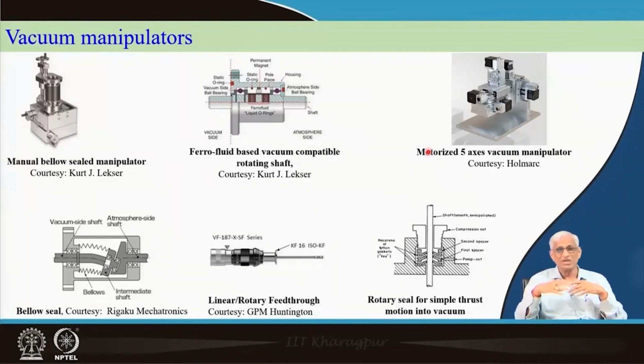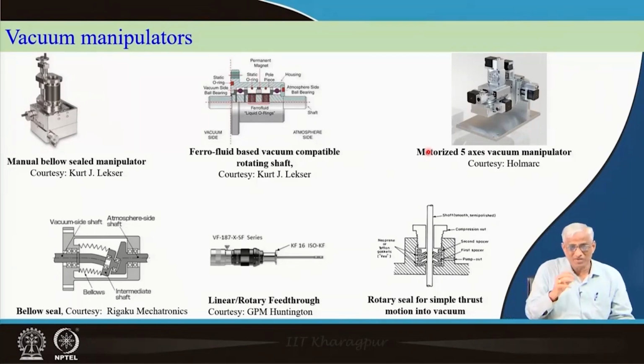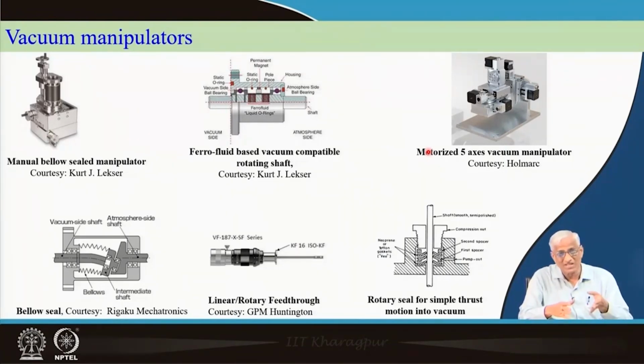If it is ultra high vacuum, all metal. If it is normal vacuum, the seal portion can be neoprene or some other Viton gaskets, like that. So, you must have a good knowledge of materials which we have already covered in the last class. If necessary, you again go to that class. Then with these things, we will go into the next class, where we will be discussing chamber design and thickness calculations. Otherwise, you will end up purchasing an unnecessarily large amount of material. Here also, you have to finalize the materials.